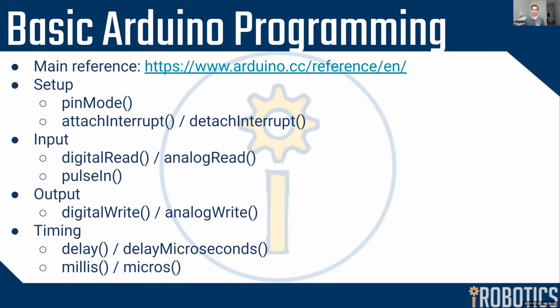And then you can have analog read, which will actually give you the analog voltage from 0 to 1024, or 0 to 255, which is just from 0 volts in little increments up to the top value, the same as 5 volts. So you can get the actual analog voltage that was at that pin, but this is only on certain pins of the microcontroller. On the Arduino Uno, I think there's like 7 or 8 pins. There's more on a Mega, fewer on a Nano, but you basically can read actual analog voltages there rather than just, is it a low or a high, 0 or a 1?